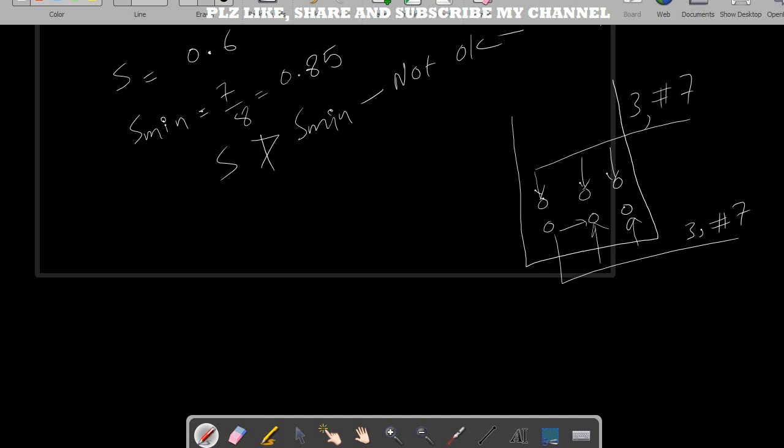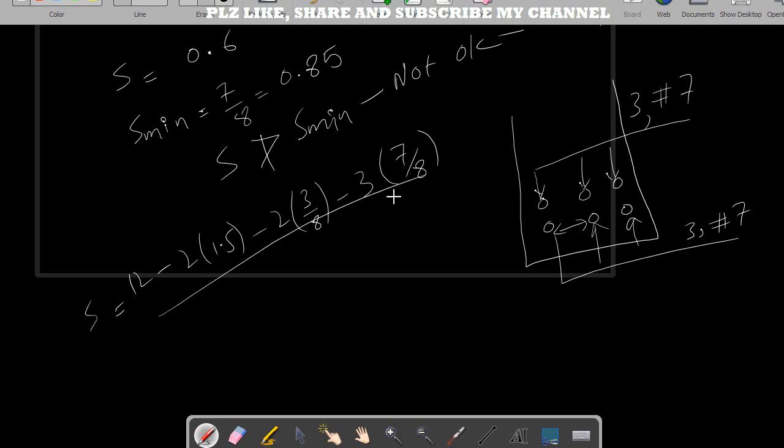So the clear spacing this time is equal to 12, which is the width of the beam, minus 2 times side cover, which is 1.5, minus 2 times stirrup dia, which is 3 by 8, minus number of bars. This time we have 3 number of bars, 3 times diameter of the bar divided by number of spacing.